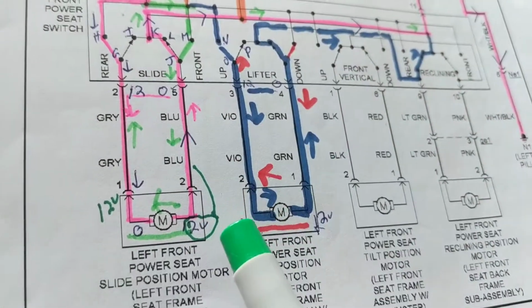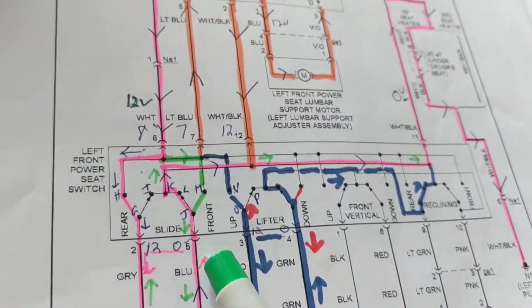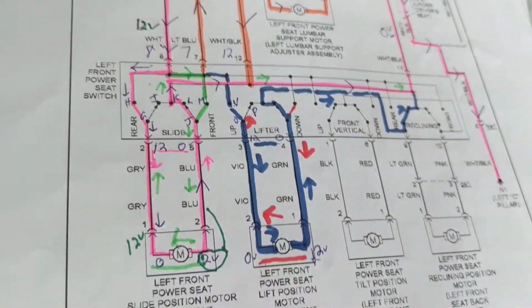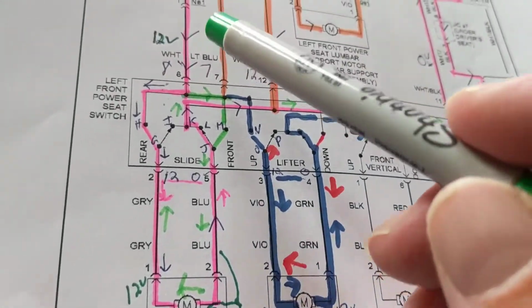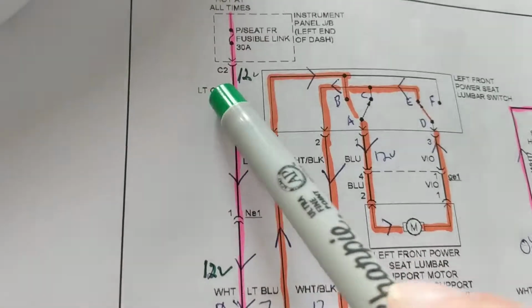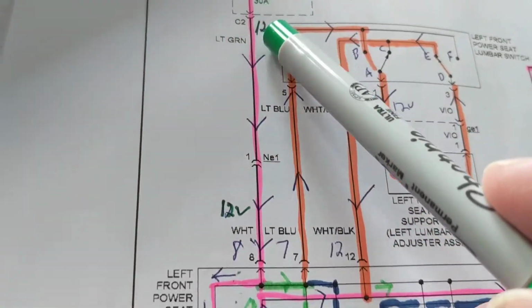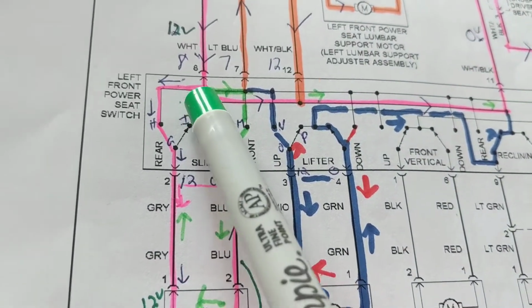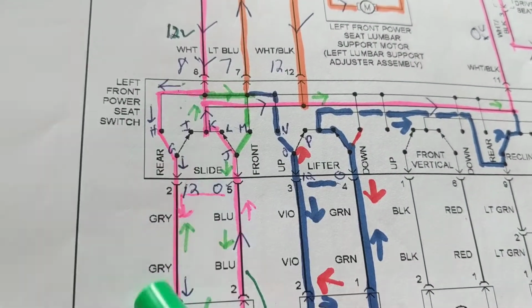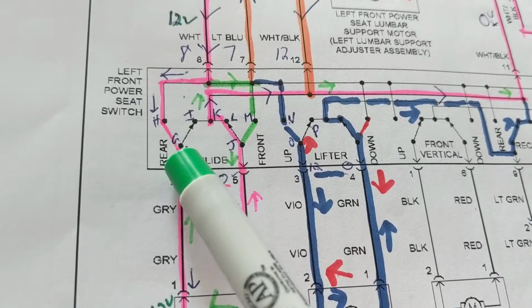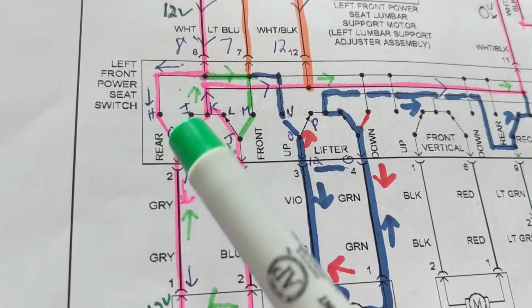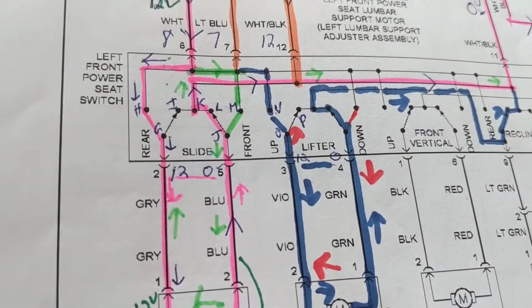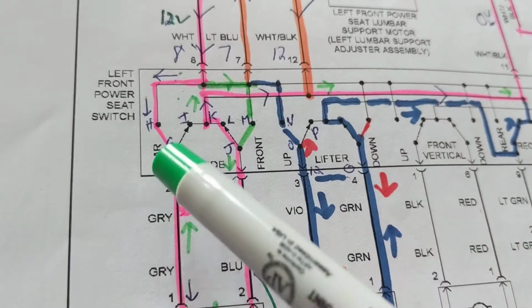So JM. Okay? Now, what are we going to follow? Which way are you going to follow? We're going to come over here. Notice one thing. This fuse is for rear, for front, for both. We come over here. Instead of going this way, we can go this way. Why not? Because the switch is in this position. We need a complete path to the motor to ground. We can't go here. It's open.